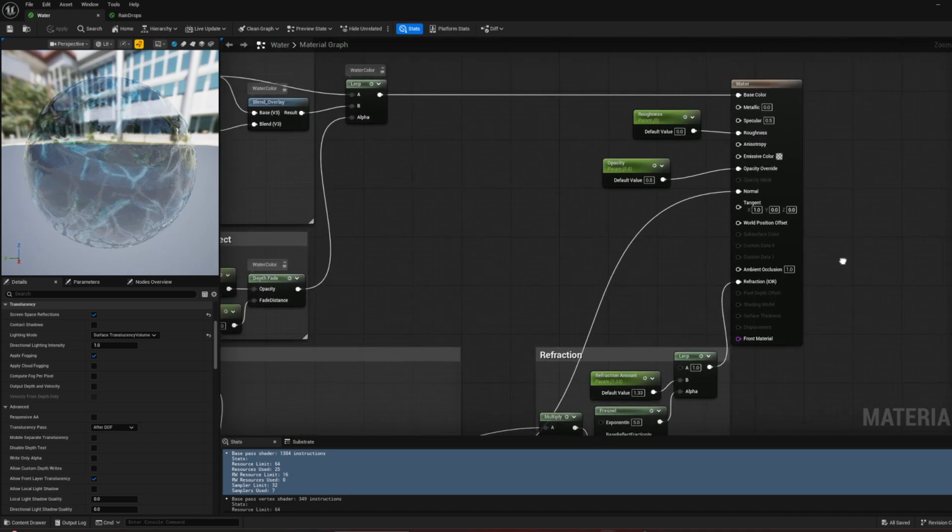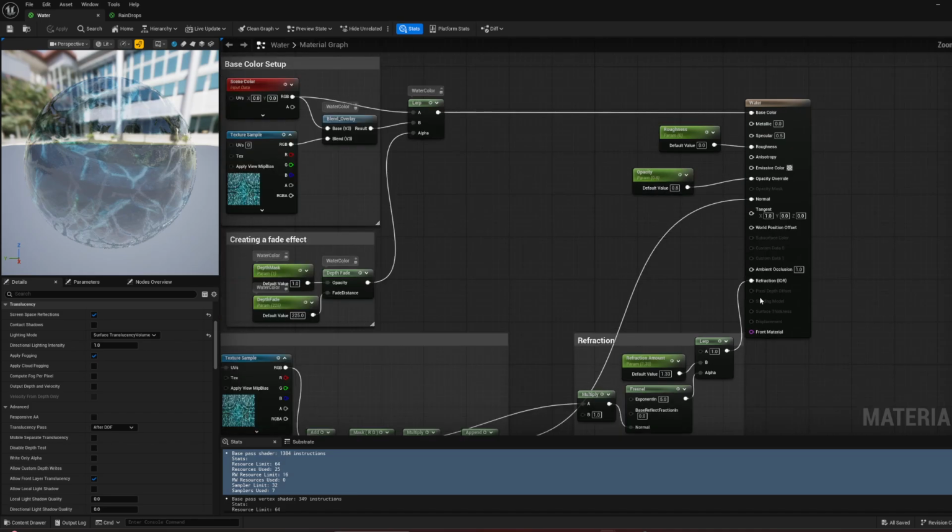On this output, we got the normal from the animated normal, and then we got the base colors. We are setting roughness to 0 to make the smooth texture of the water, and we are using opacity 0.8. We also have specular of 0.5 to give a natural reflective surface to the water.